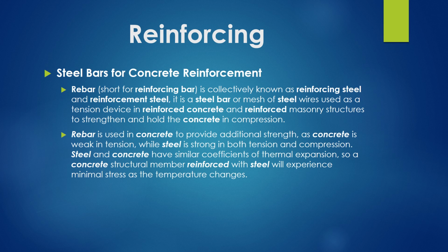Rebar is used in concrete to provide additional strength as concrete is weak in tension, while steel is strong in both tension and compression. Steel and concrete have similar coefficients of thermal expansion, so a concrete structural member reinforced with steel will experience minimal stress as the temperature changes.